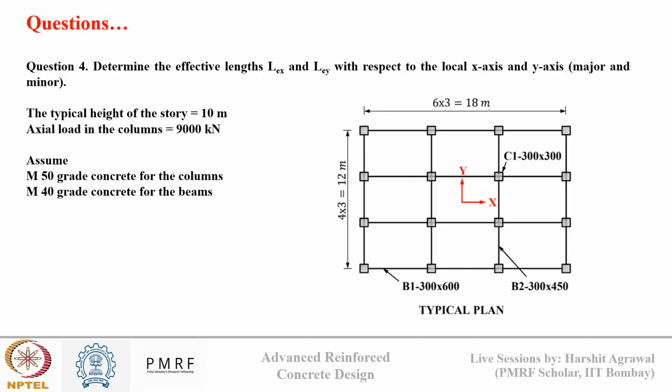Let's see the application of this entire theory: how to calculate lateral displacement, then how to calculate stability factor, and then how to calculate the effective length of the column. We'll see. The basis of this numerical is the same as you saw in the NPTEL recording, but the values here are different. There you talked about a non-sway frame. Here we are talking about a sway frame. We'll see what changes come.